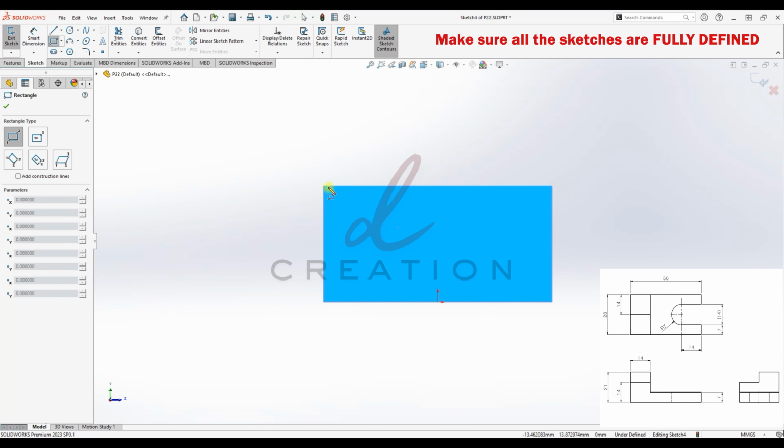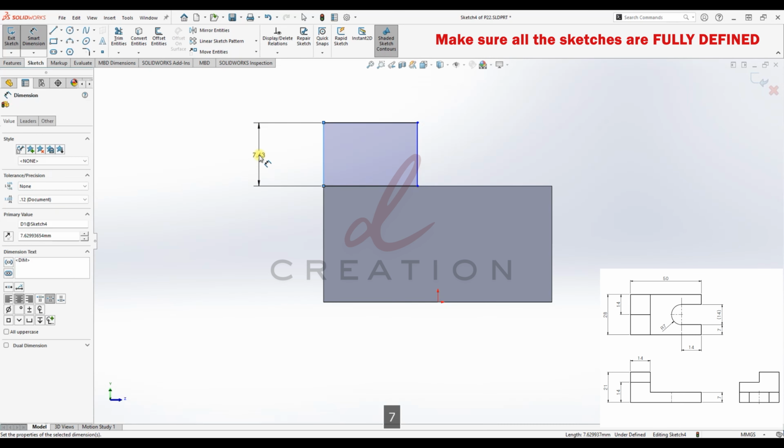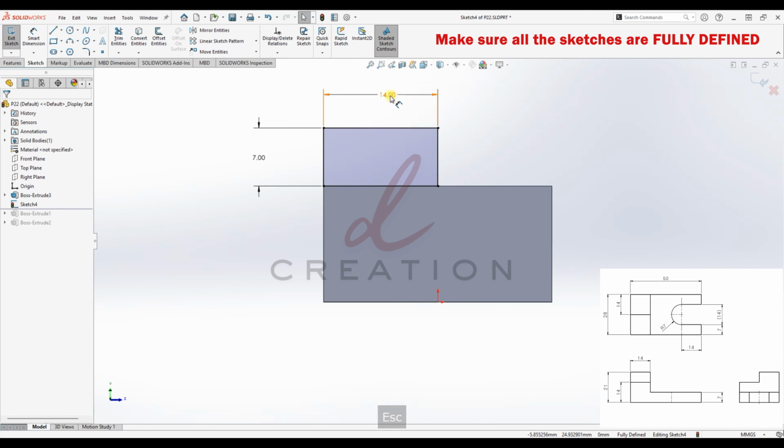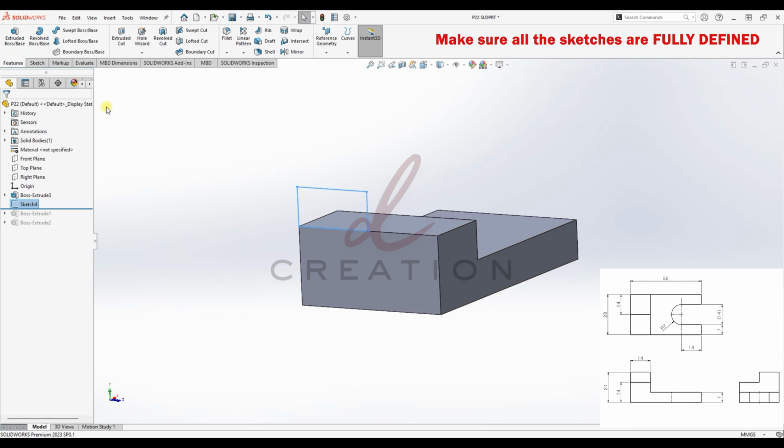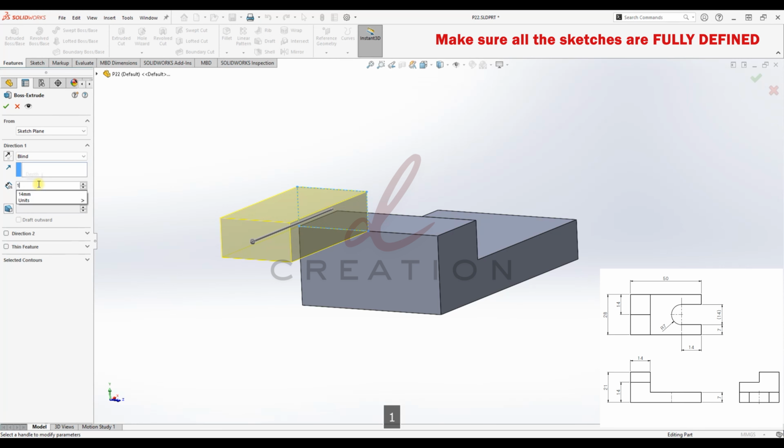I'm going to select the corner rectangle and set this point like this. The height of this is 7, the length is 14, and our sketch is fully defined. Exit sketch, extrude cut, using blind and 14, change direction.